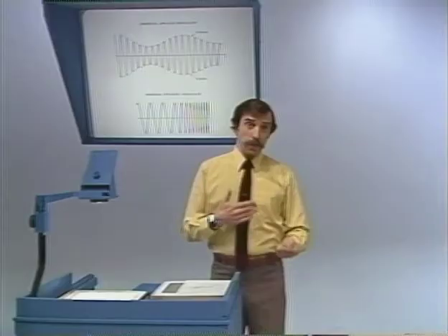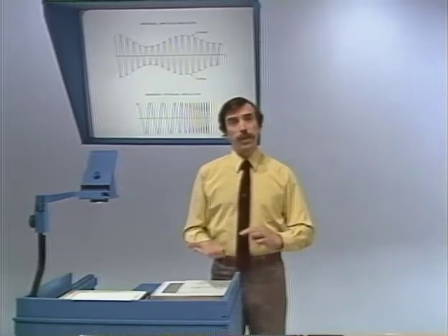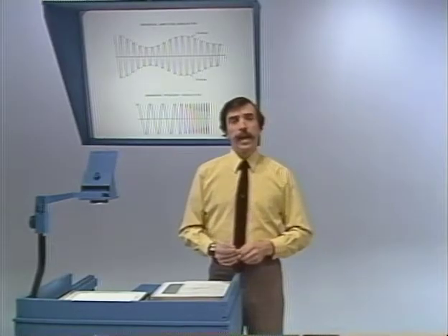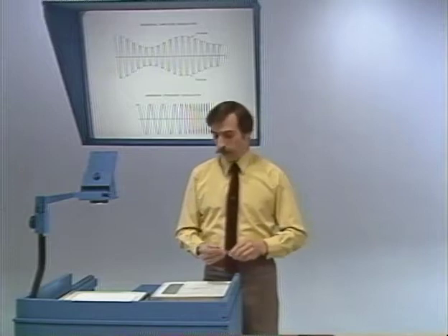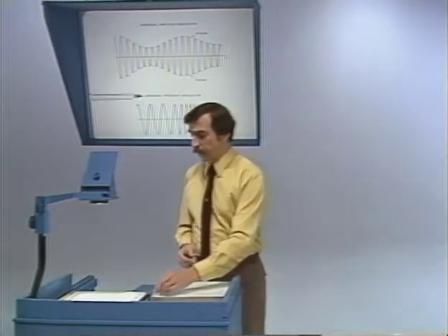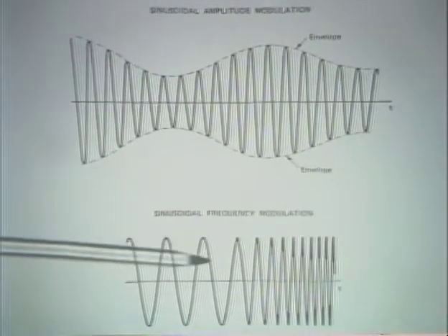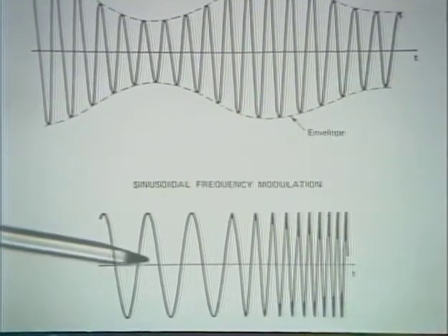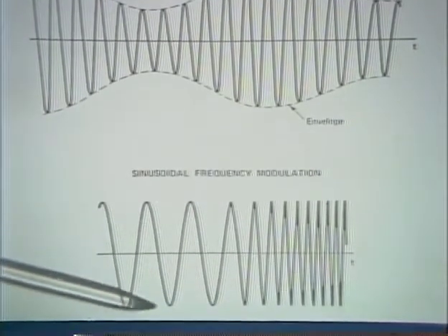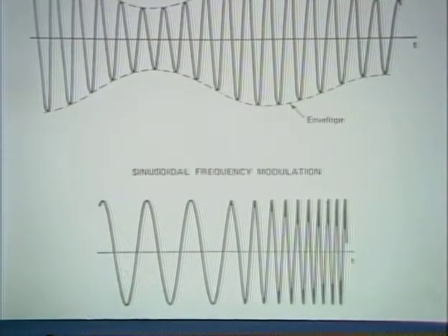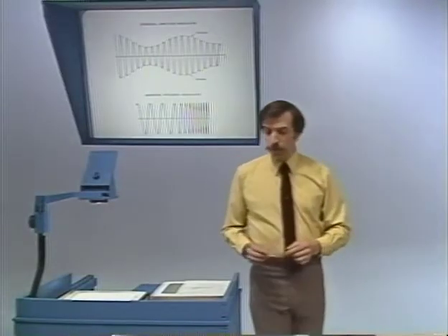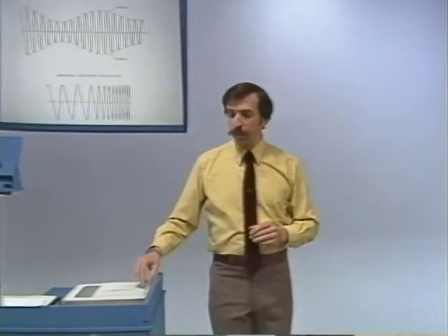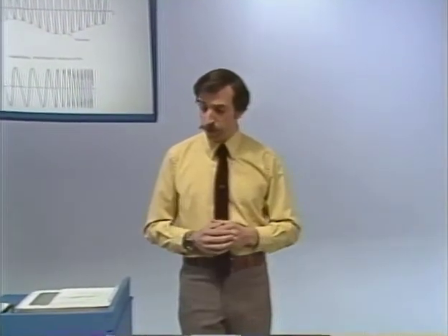Now, alternatively, we could think of varying either the frequency or the phase of a sinusoidal signal, again with another signal. And what that leads to is another very important notion, which is referred to as sinusoidal frequency modulation, where essentially it's the frequency of a sinusoid that's changing depending on the signal that we're using to modulate this sinusoid. Now, sinusoidal amplitude, frequency, and phase modulation are extremely important topics and ideas in the context of communication systems.